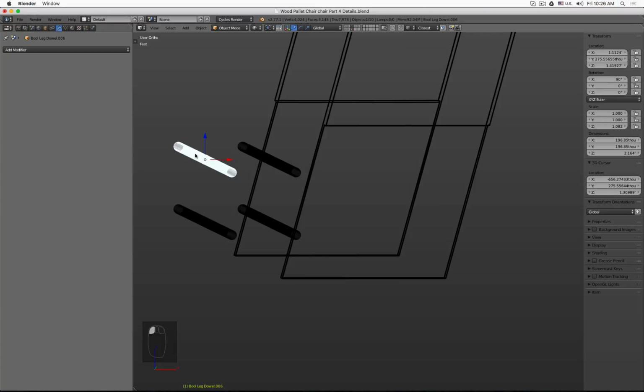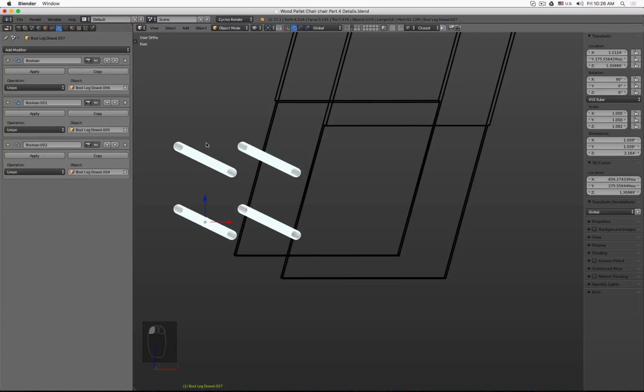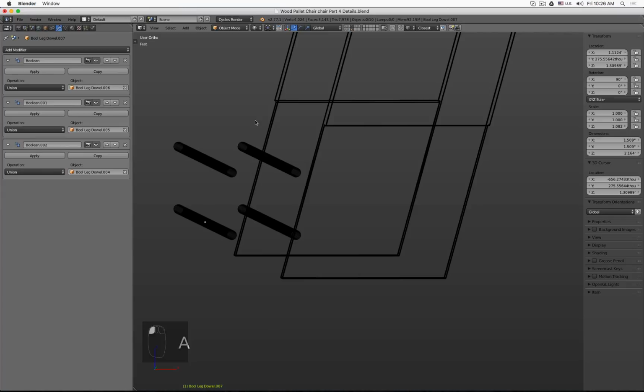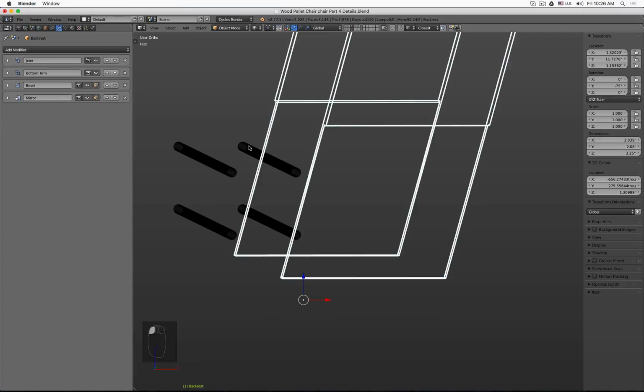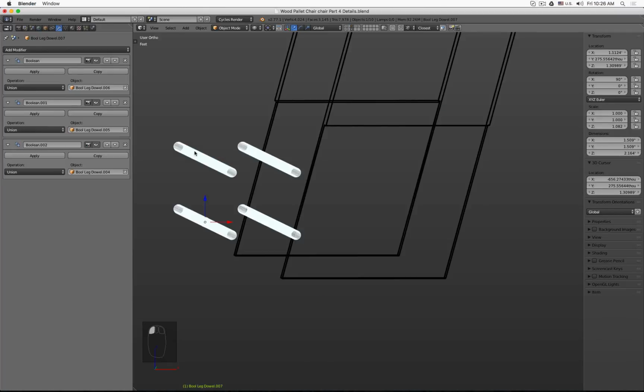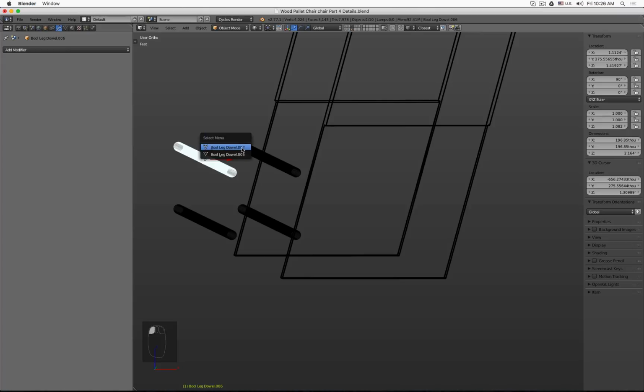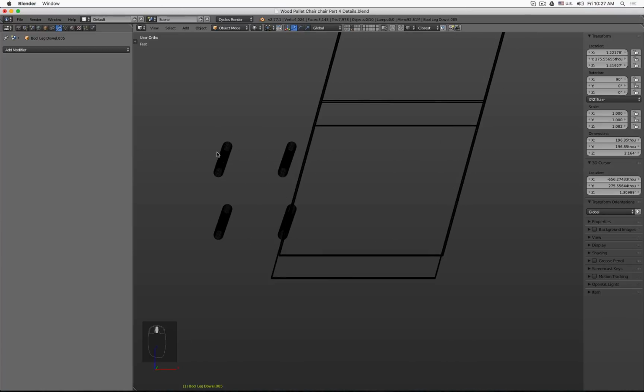So there are multiple ways how we can select this one. When you hold the Alt key and then left mouse button click on an object, it gives you a list if there are more objects. So number 1 or number 2, you see we want this one and this one. So it's one way. So this is what you want to have selected. Or in case you simply say B, drag a selection, and then this one is selected as well.